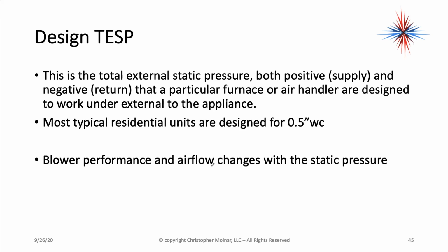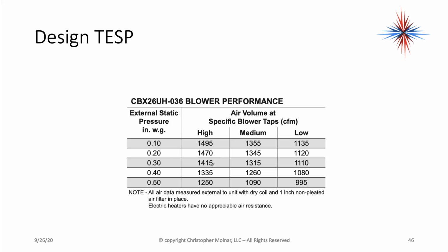Inches WC. Design total external static pressure, both positive and negative, for a particular furnace or air handler, is designed to work under external to the appliance. Most residential units are designed for 0.5-inch water column. Okay, blower performance and airflow changes with the static pressure.